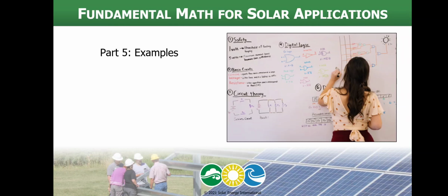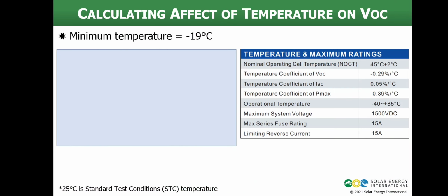Our class on fundamental math for solar applications, where we're going to take the things that we just learned and apply them to some real-world examples from the PV industry. First, we're going to calculate the effect of temperature on the open circuit voltage of our module.